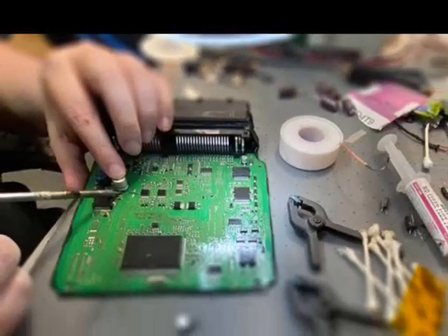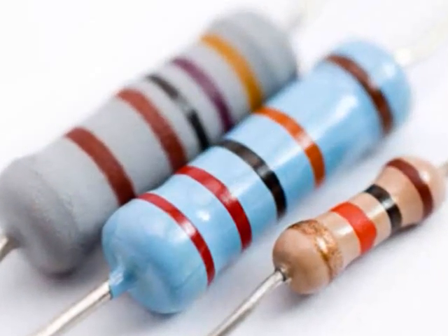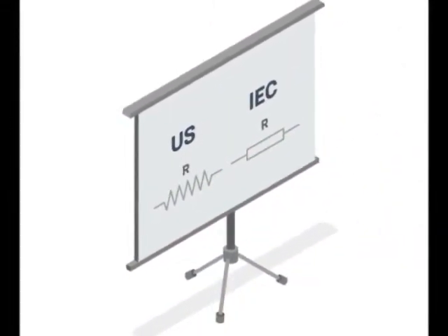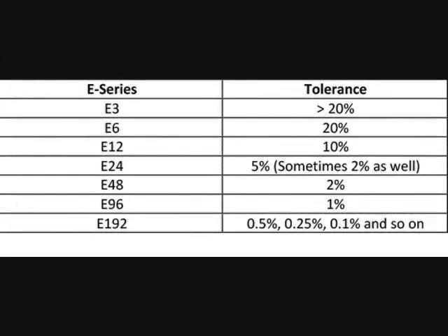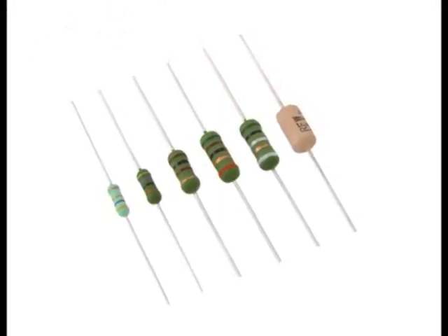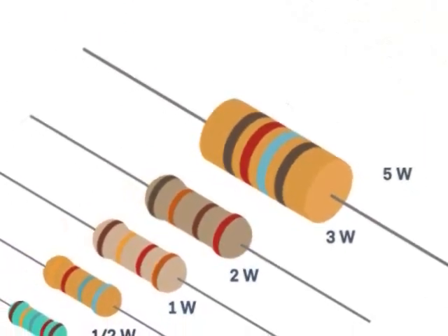The names of carbon composite resistors are written with the prefix CR, for example, CR 10 kΩ. These types of resistors are produced in the same types as E6, 20% tolerance or accuracy, E12, 10% tolerance, and E24, 5% tolerance. Their tolerable power is from 0.25 watt to 0.5 watt.